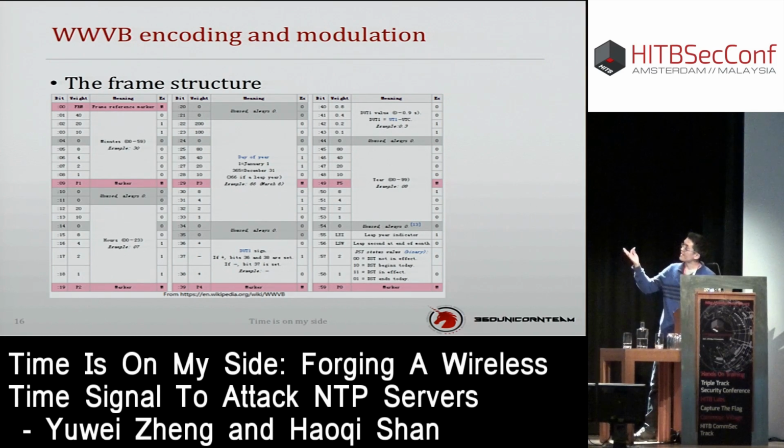each frame contains the minutes, hour, year, day of year, and day of week. The final bit is also a marker. So if the receiver gets 2 sequential marker bits, it means that a new frame is about to be received.